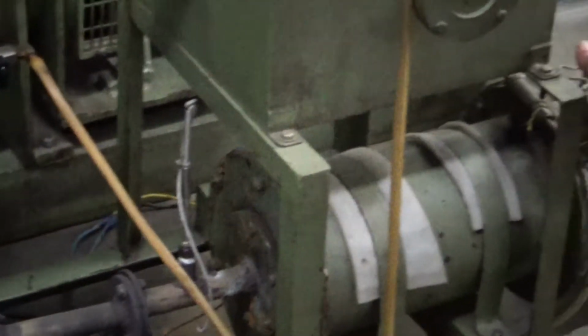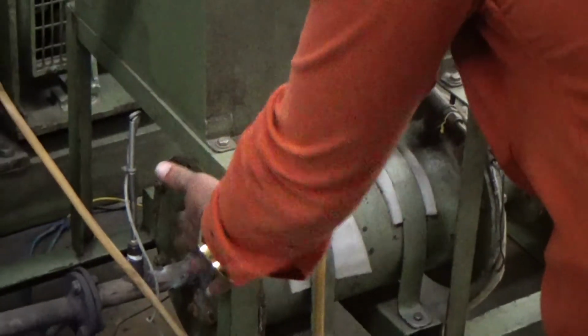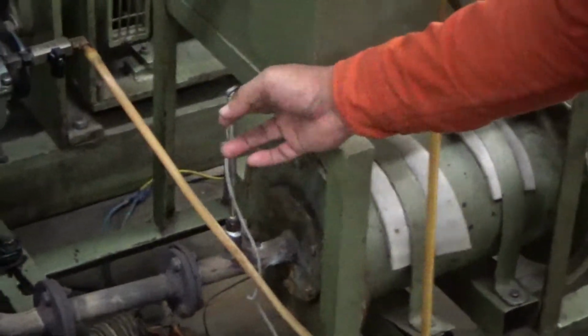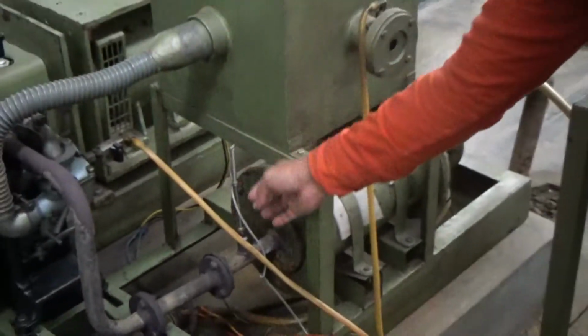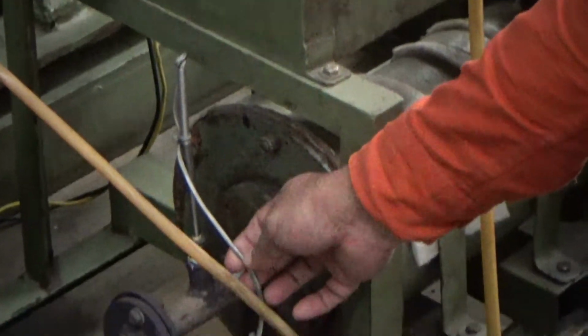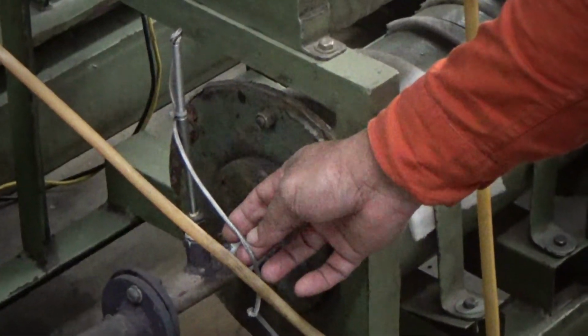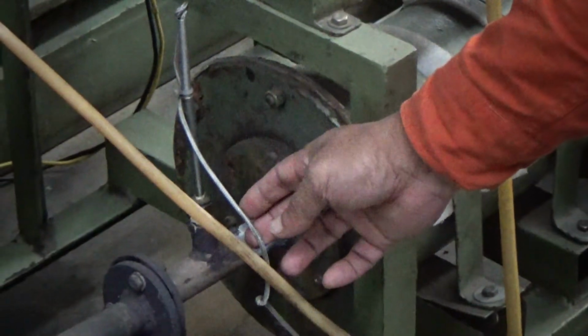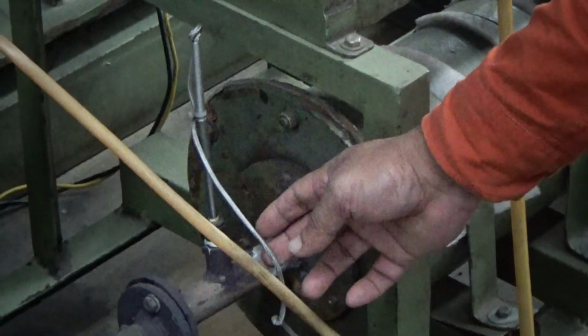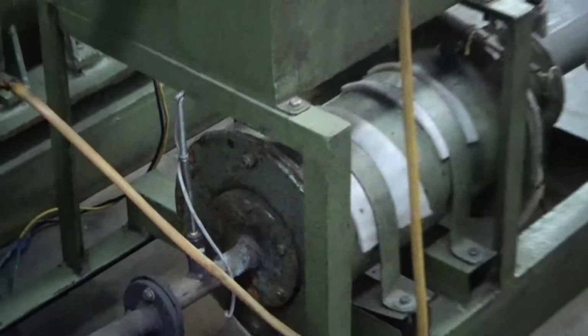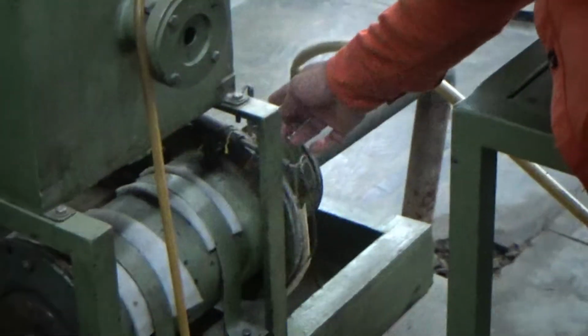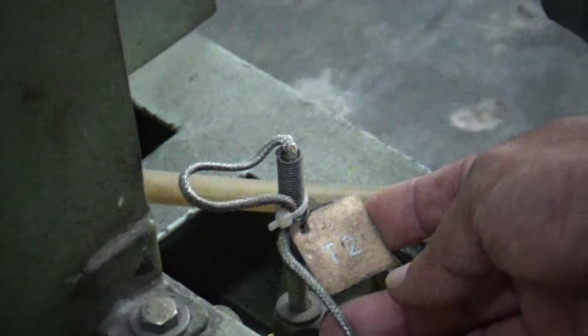So this is the exhaust calorimeter, and we have the T1 sensor, the inlet temperature directly from the engine. The exhaust gas will directly hit the calorimeter, that's the T1 sensor, and we have the T2 sensor just downstream of the calorimeter.